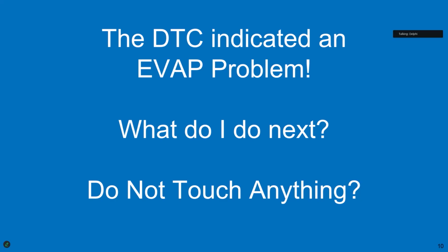And this is my rule, and I mean this sincerely to you out there working in the industry. Do not touch anything. You're getting paid. You're going to probably charge a flat rate diagnostic fee for the EVAP system. I would do that if I were you. If you touch anything, as simple as turning the cap, you might already fix the problem and you don't know it, but you still need to go through and test it to verify it.